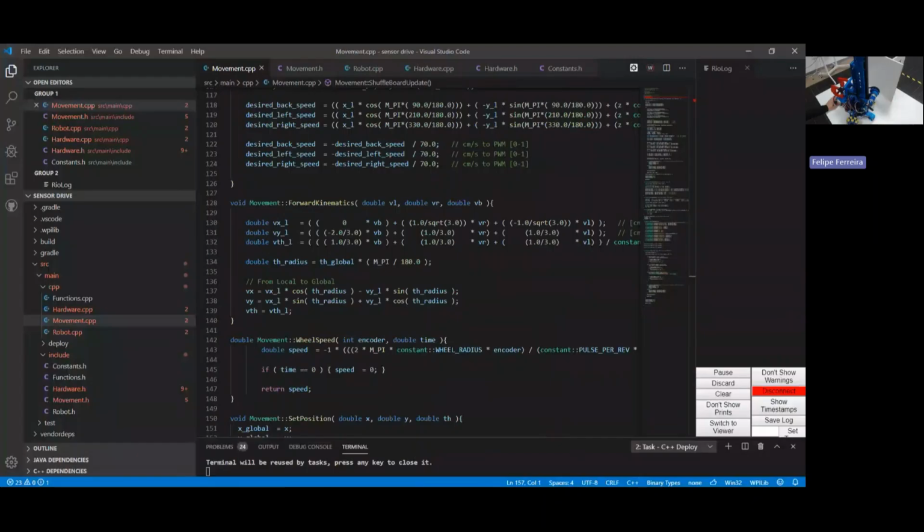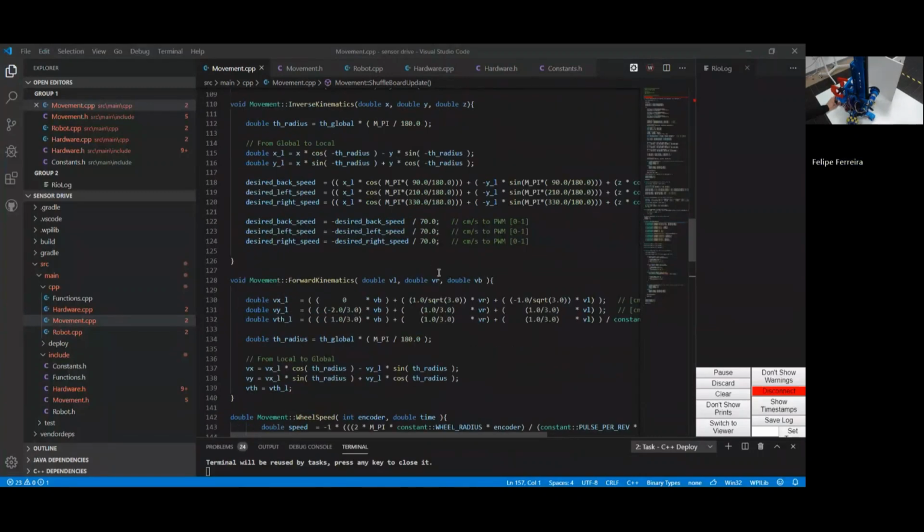You just apply a speed to the wheels, and then inshallah your robot's gonna behave the way you want. If you want to improve, you should add feedback here to control the speeds better. So we would put a PID control, a proportional control, whatever could make sure that the robot will reach the speed.